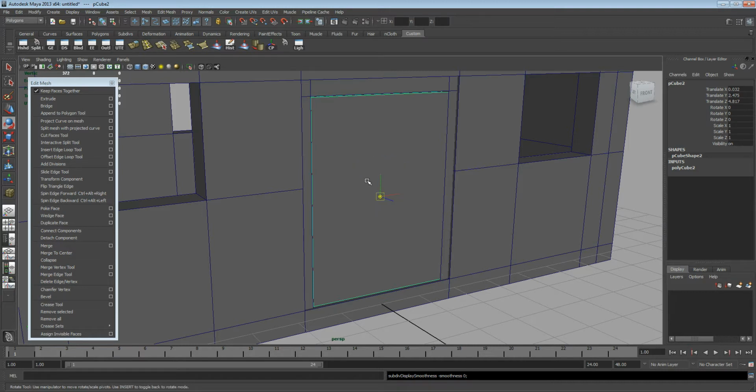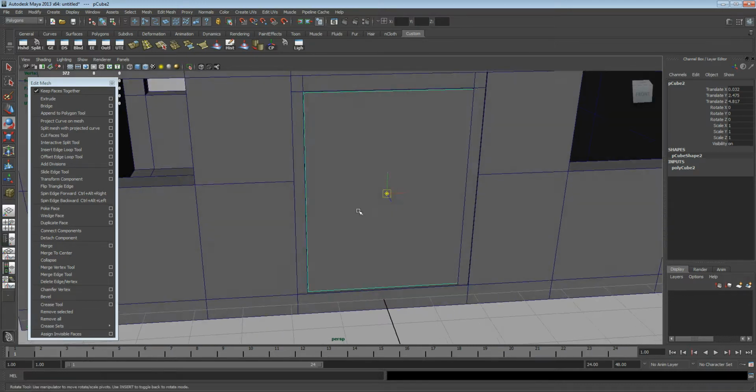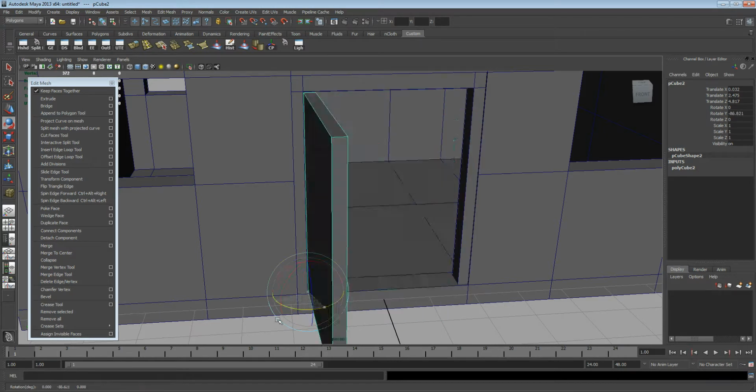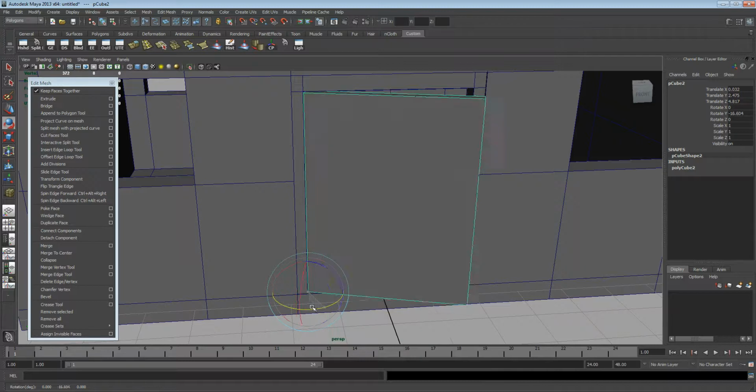There we go. So once you have your insert key, you can either snap to point or hold down your V key and move it to the point here, and hit your insert key again. Now once you open up your door, it will open the right way.